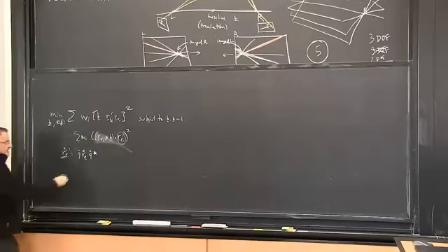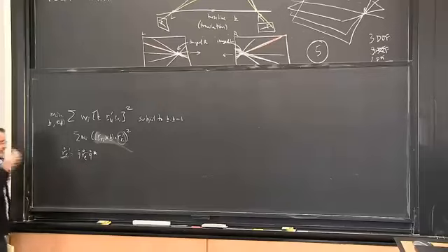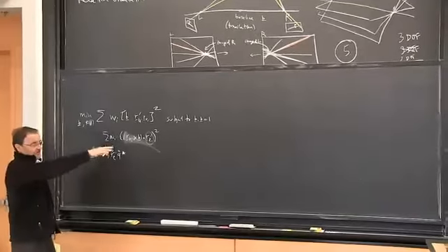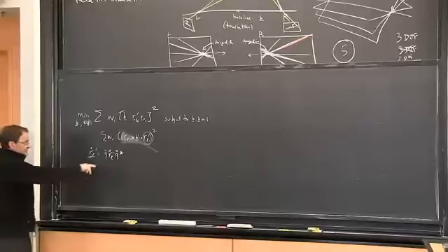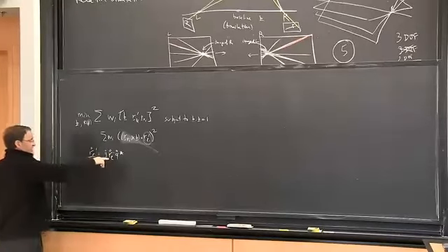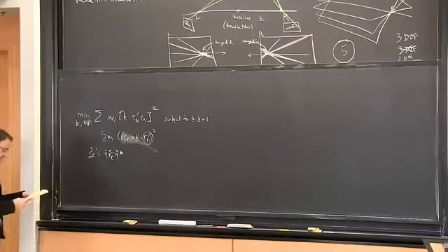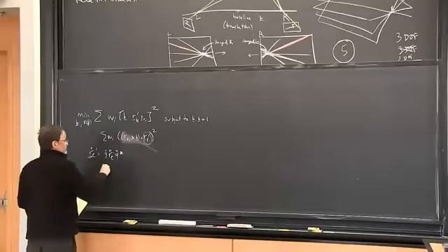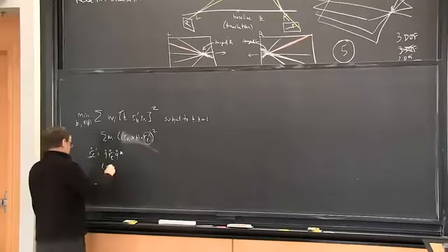Right, so if RL is the thing that I'm actually measuring in the left coordinate system, since everything over there is expressed in the right coordinate system, I have to rotate it into the right coordinate system, and I can do that using quaternions. Okay, so let's call this triple product T for convenience.